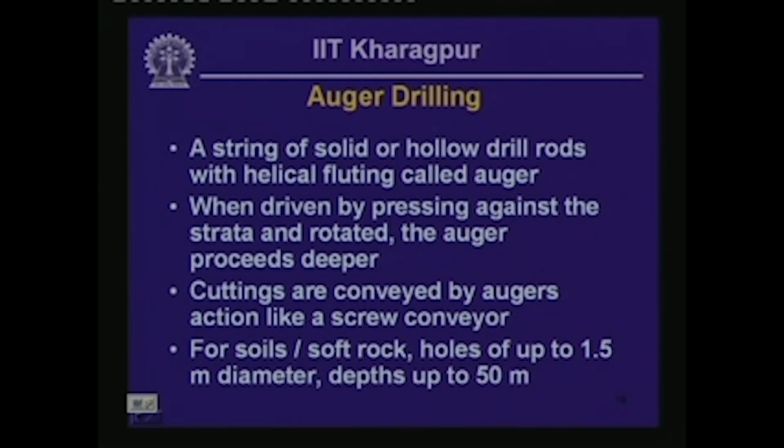And actually, as the depth increases, the auger equipment becomes quite heavy and unwieldy, and the power requirement increases quite substantially. As a result, the auger drilling process starts to become uneconomical as the depth increases to beyond 30 meters.